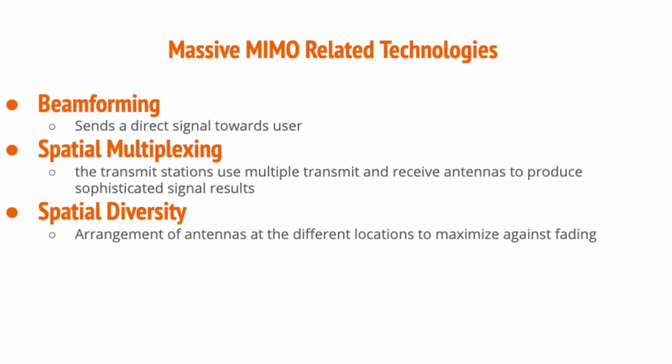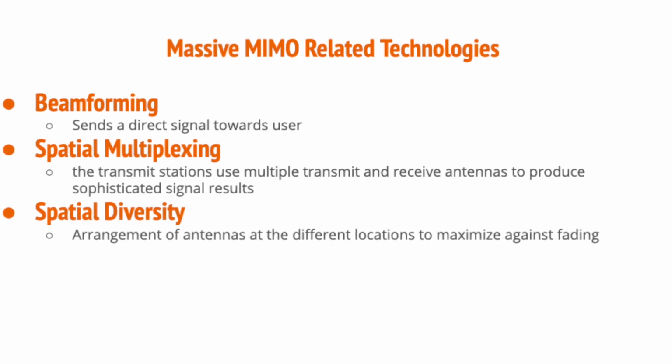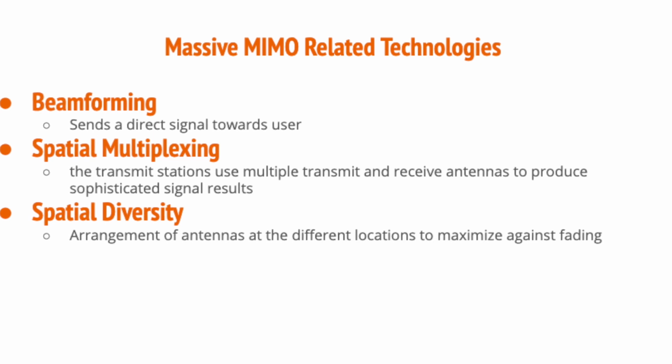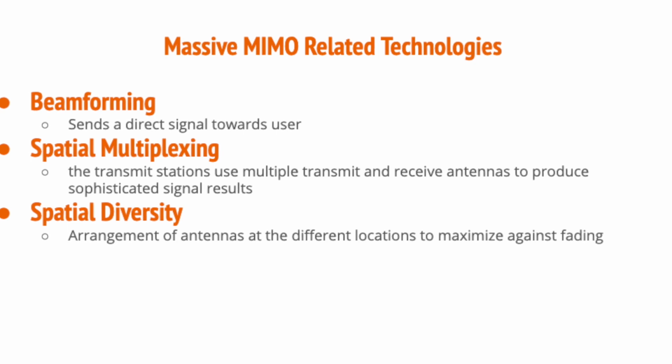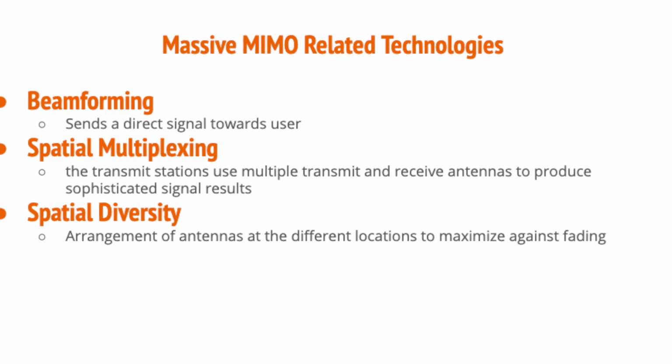receiver. Spatial multiplexing can be used without channel state information at the transmitter, but can be combined with pre-coding if channel state information is available. Spatial multiplexing can also be used for simultaneous transmission to multiple receivers, known as space division multiple access, or multi-user MIMO, in which case CSI is required at the transmitter. The scheduling of receivers with different spatial signatures allows good separability.